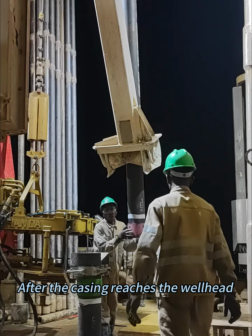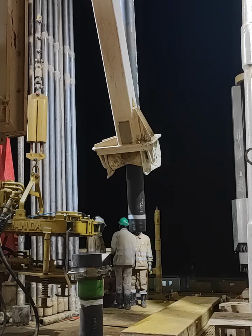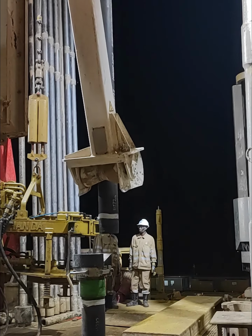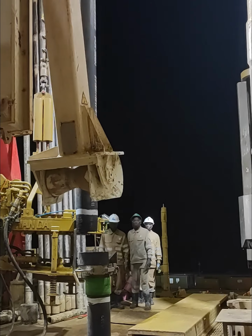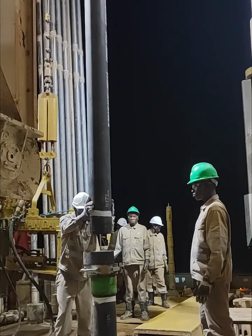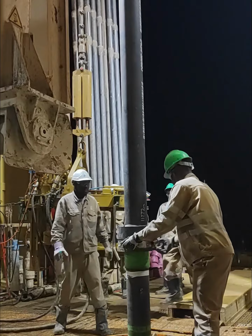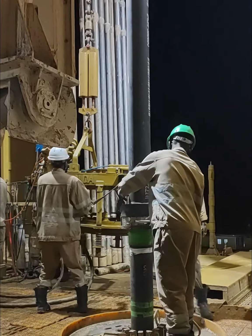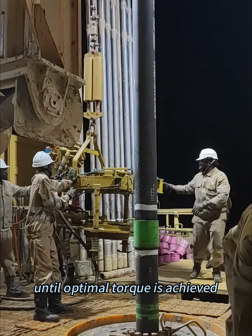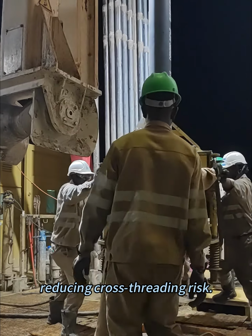After the casing reaches the wellhead, remove the thread protector and install the casing stabbing guide. After aligning the casing, use power tongs for makeup until optimal torque is achieved. Power tongs can reverse rotate to engage threads, reducing cross-threading risk.